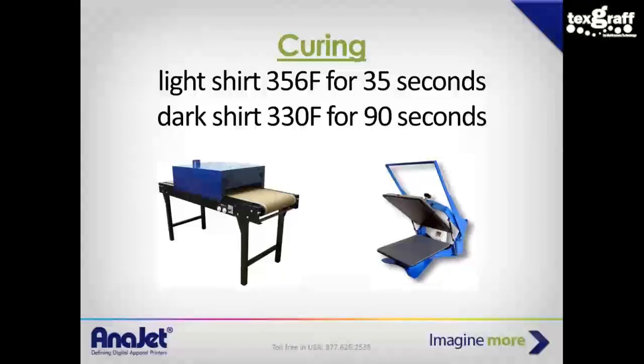If you ever have a wash problem, if you ever have a customer that is saying, man, I washed this 5 times and it's all washed out, it doesn't have anything to do with the manufacturer-specified ink. It doesn't have anything to do with the printer or the graphic setup. It is all based off the curing, because there's a literal chemical reaction: applying the heat binds the ink to the fabric and evaporates all the water out of the ink. So the only thing left is the pigment.